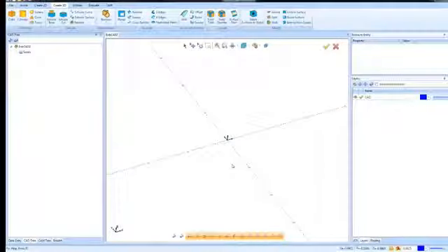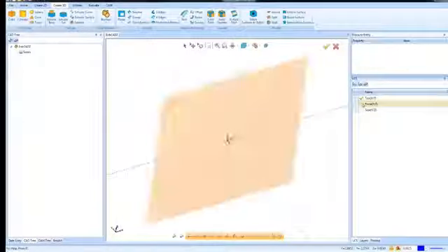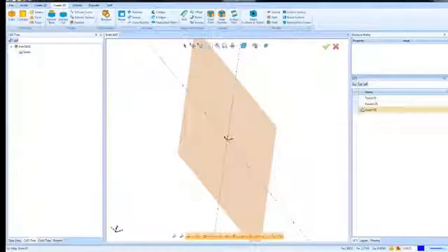Again, when it comes to design inside of BobCAD, by default, the user coordinate system, or the plane that you're drawing on, is the XY plane. So the first topic that I wanted to cover is when you're creating your designs in 3D, you can utilize different planes, different construction planes or drawing planes, in order to aid in the design. So you can create a sketch on the front plane or the side plane, and as you do extrusions, help you with your overall design process.